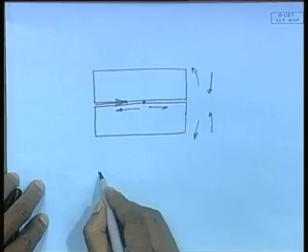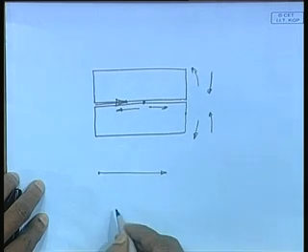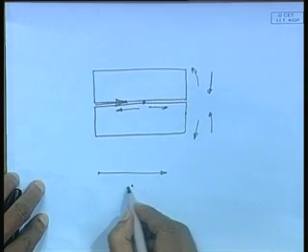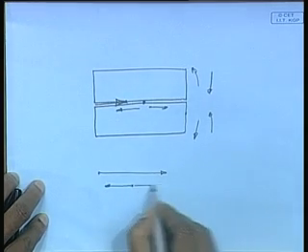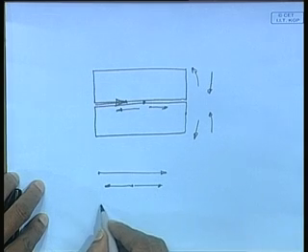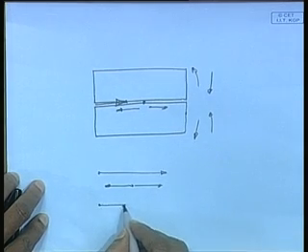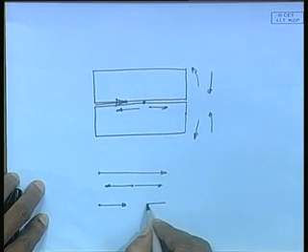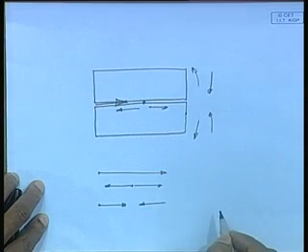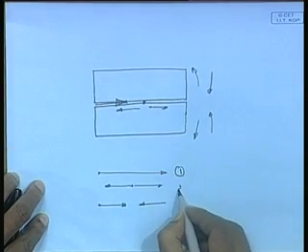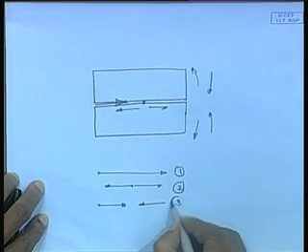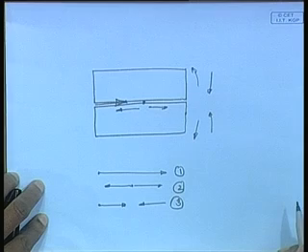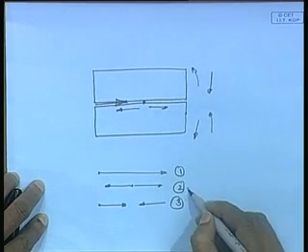One is from one end going towards the other end, another would be from the center going outwards, another would be simultaneously going inside from outside. They are the three sequences essentially for this simple case of butt welding, of which this is ideal.